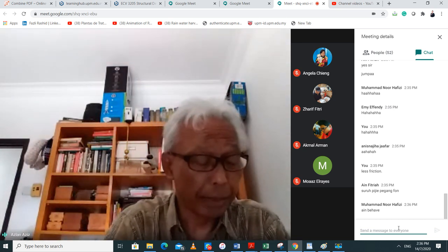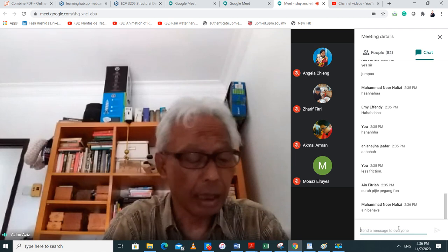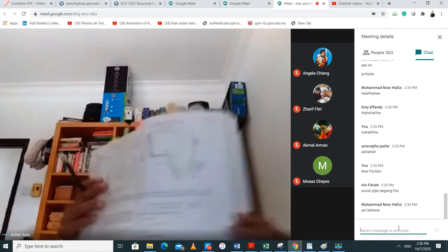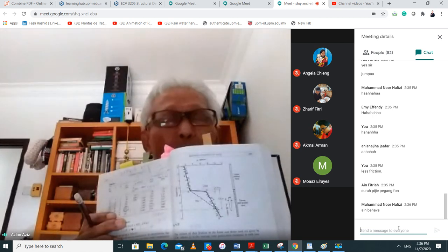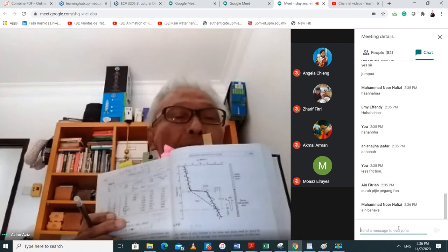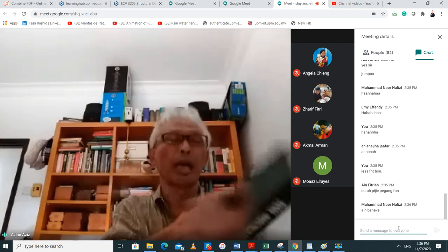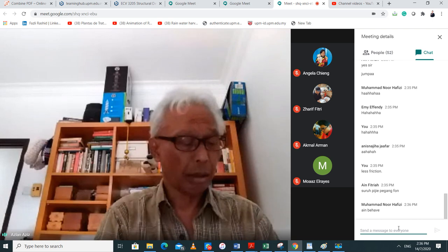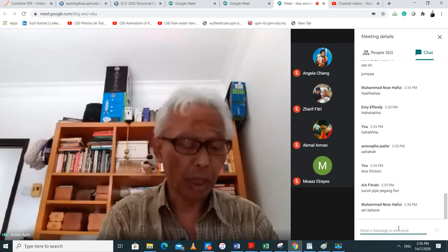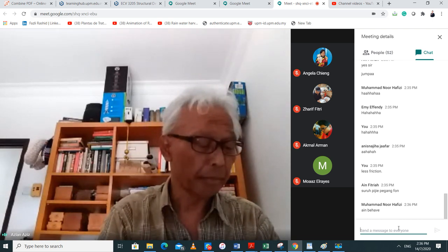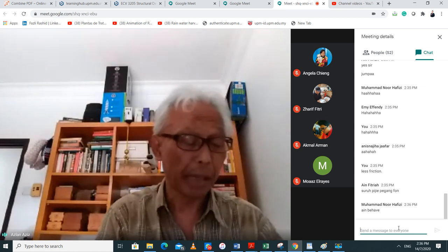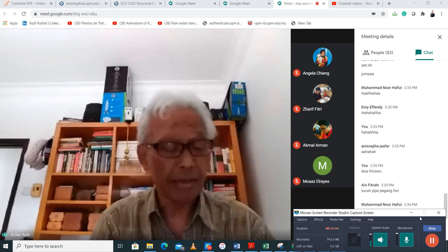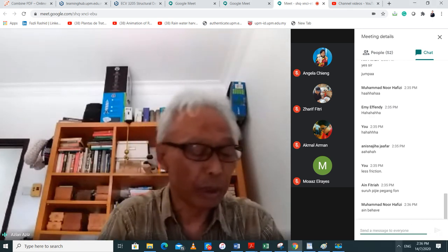Results of cone penetration test at a particular site are shown in figure 8.25. You see that figure there, 8.25. That's how the CPT result with depth is. Remember all that curve? All right. Now, on the basis of this result, to what minimum depth should a 600 millimeter diameter concrete pile be driven in the dense sand if the shear zones are to be fully developed?